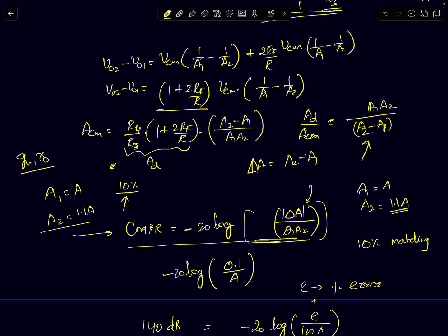So there, if you are going to build an analog circuit in a mixed signal chip, you will normally be using devices that the digital guys will be using. So those devices can have higher mismatches. They are not normally optimized for analog performance, so they tend to be poorer in performance. So that's why I've assumed some mismatch. They will have higher mismatches. So here I've taken a 10% mismatch.